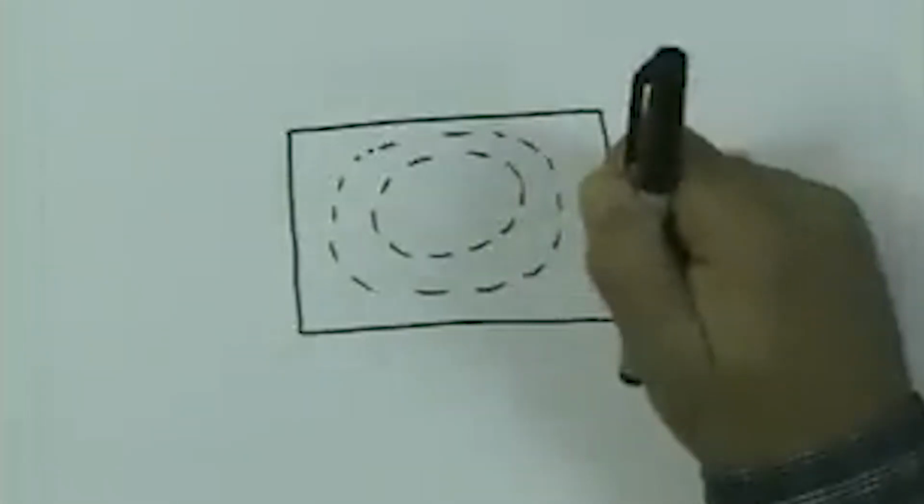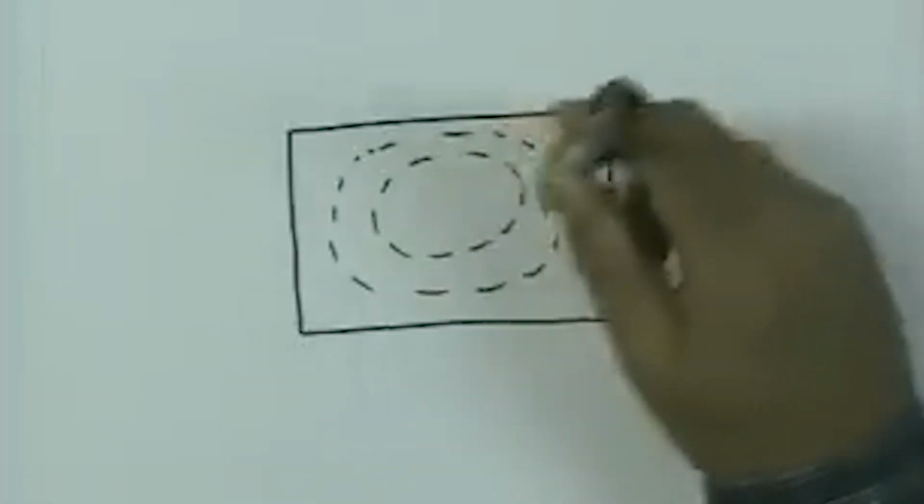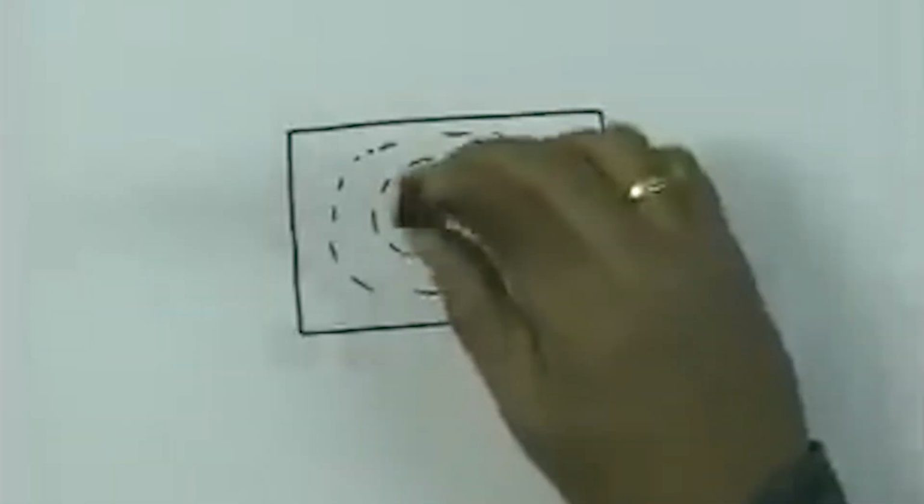So the only possibility which can exist is a displacement current to support these magnetic field lines, and this displacement current must be flowing in that direction. But the displacement current would require an electric field going in that direction, which we already denied for the transverse electromagnetic mode. For the transverse electromagnetic mode, the electric field also lies only in the transverse plane. That means it does not have a component perpendicular to the plane of the paper.